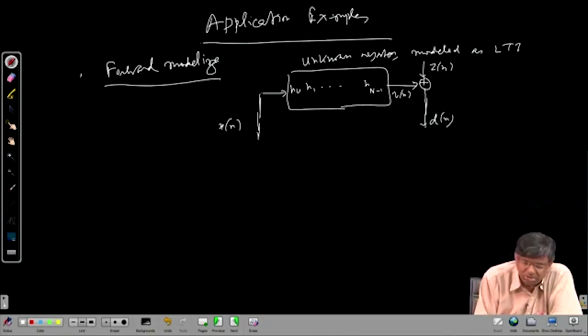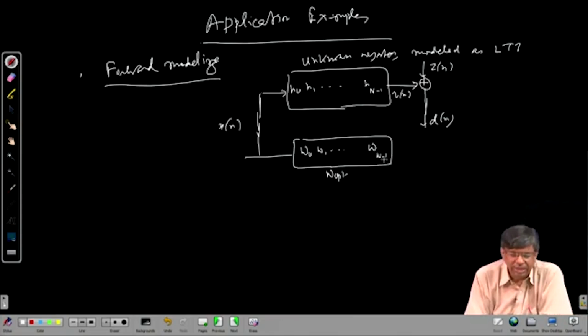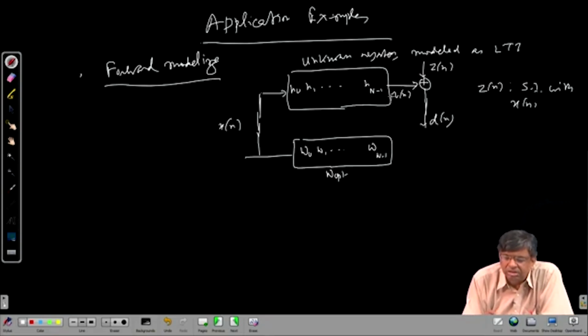Now, suppose my question is you want an optimal filter W opt, it has W0, W1 dot dot dot W n minus 1. It is assumed Xn is 0 mean and therefore Vn is 0 mean, Zn is statistically independent with input, very natural, is a noise generated inside the system, it has nothing to do with the input. So, you can assume that to be independent of each other, all right.